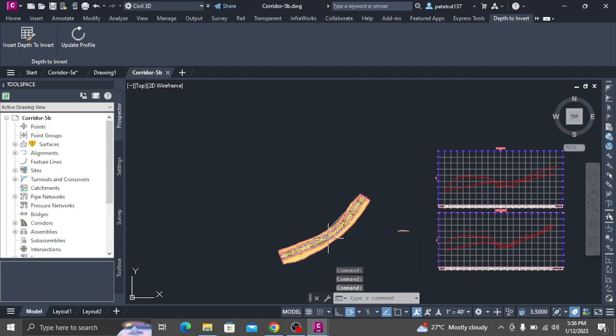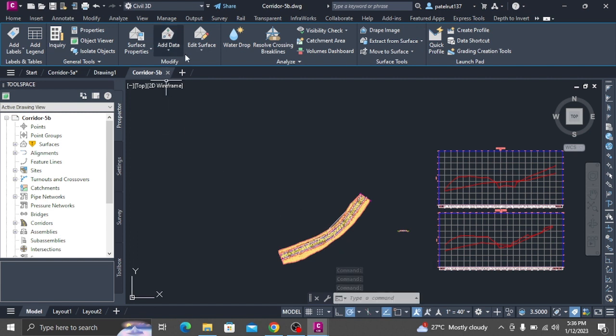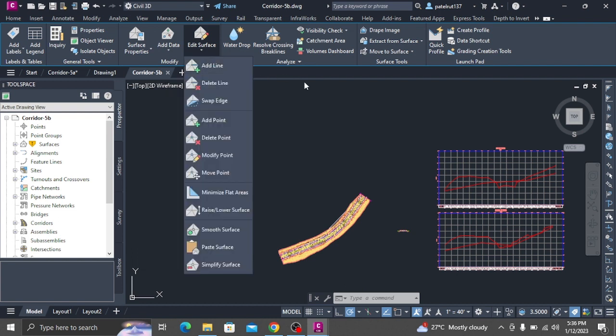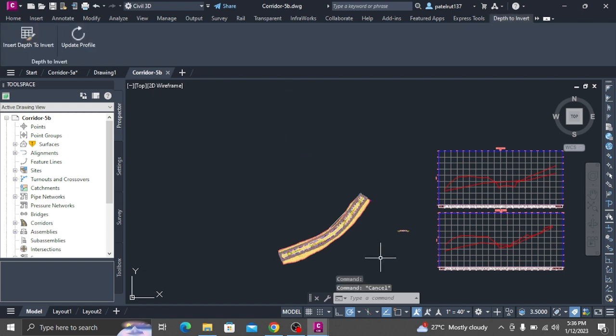In the drawing, select the corridor. Click Corridor tab, Modify Corridor panel, Corridor Surfaces. In the Corridor Surfaces dialog box, on the Boundaries tab, select the Corridor 1 Paved surface. Right-click. Click Add Interactively.